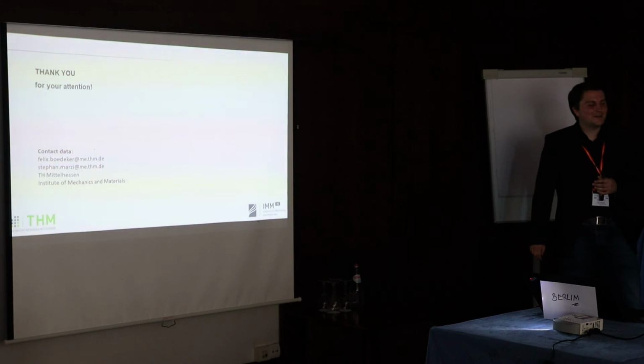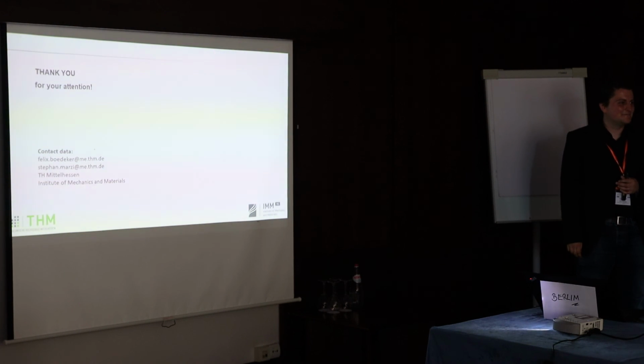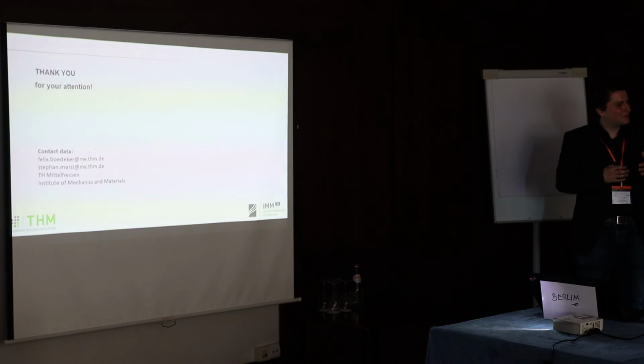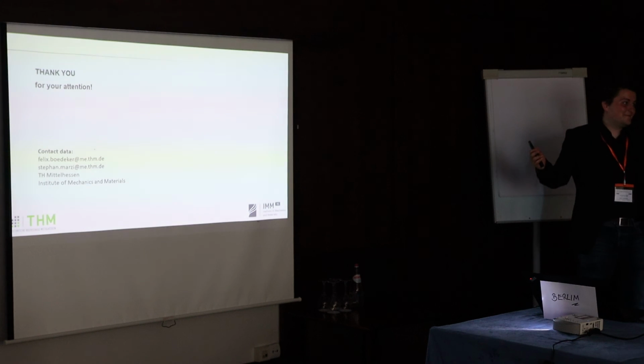This is highly problem and algorithm dependent. In the literature it's usually expected to be faster, but I haven't done my simulations in FEM and I haven't compared this, so I don't know how it is for my specific problem. So you don't know if you get any benefit, basically. I think all the trouble going into the frequency domain with FFT, you should know how much benefit you get out of it. Yeah, usually it's expected to be faster, but it somehow depends. It depends on basically the material contrast that you're having.